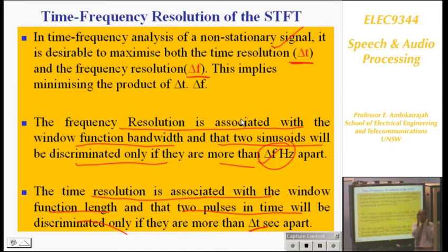Okay. Small window means what happens? Small window means cutoff frequency is large, but 1 over cutoff frequency or 1 over bandwidth is small, so good time resolution. Do you understand? So small window is a large bandwidth, but 1 over bandwidth is small, therefore it's a good time resolution. So frequency resolution means large window, time resolution means small window. Okay? Important.